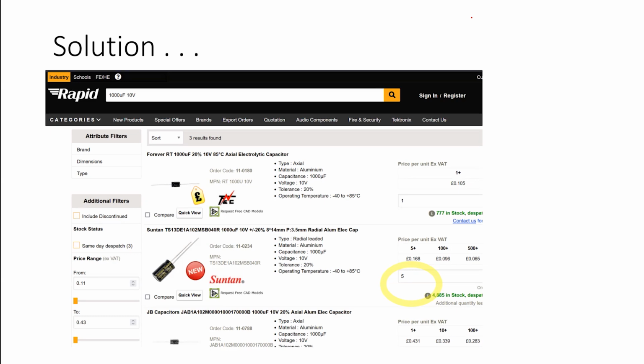The supply that I'm working on uses a 10-volt capacitor. It's a 5-volt supply, so a 10-volt capacitor is plenty of overhead. But the capacitor that I had to put in was a 25-volt capacitor, so it's got even more overhead in it. There's a thing called derating in electrolytic capacitors, whereby you should always give a little bit more voltage than you expect to ever see.